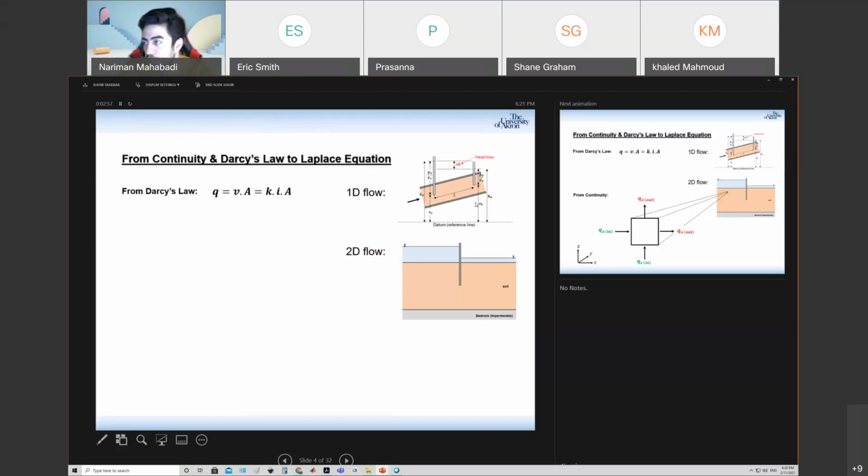So how do we get this total head? We're going to put in a piezometer. The depth of the water or fluid in the piezometer will give you the pressure head. We're going to have some reference line to take the gravity into account, right? And by summing up these two values, I can calculate the total head, or total energy, of my fluid at this specific point. So HA is my total head at point A. For point B, this is my total head.